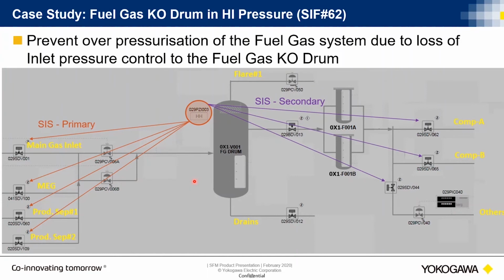But if I go and study the cause and effects for this particular safety function, I see that there are secondary elements to it. So cause and effect also tells me that those three valves should also be shut down. The SRS, however, the SIF is this, just the orange one. There are secondary elements, and then of course there is an interlocking function that is programmed within the DCS and says in these kind of cases shut those PCVs manually, which means put the PIC to manual, 0% output, shut them until we reset the trip.